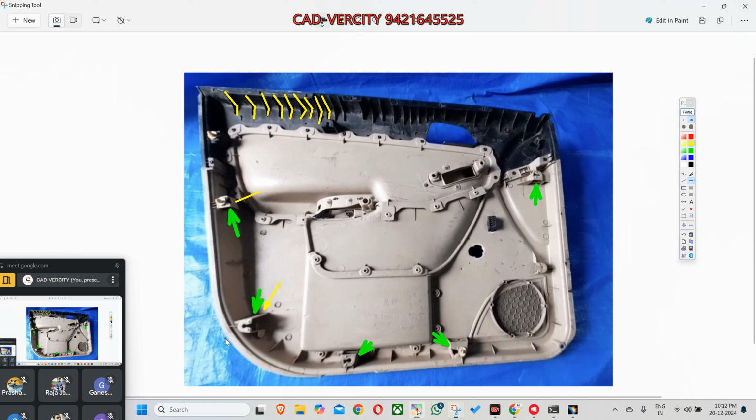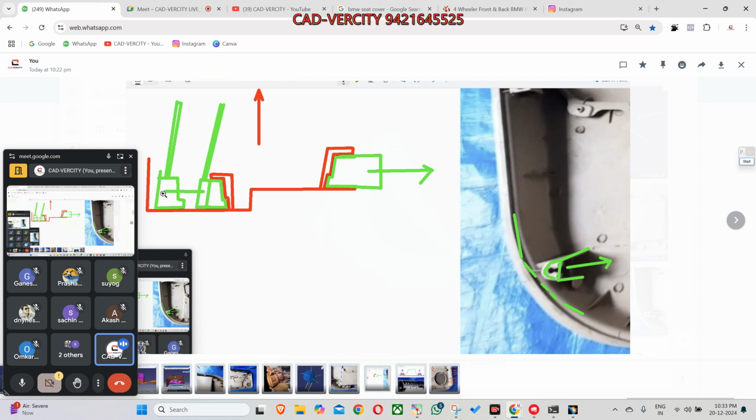Here you can see. Just a minute. The video is too fast. Can you see the pins are in angle? Yes or no? Is it vertical or are these in angles? Angles. Why? Did you notice why I'm drawing this pin in angle, like this? Why not vertical? Yes, because while moving the mold, gradually it will push the lifter outside.